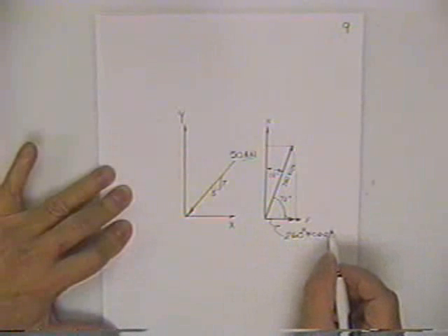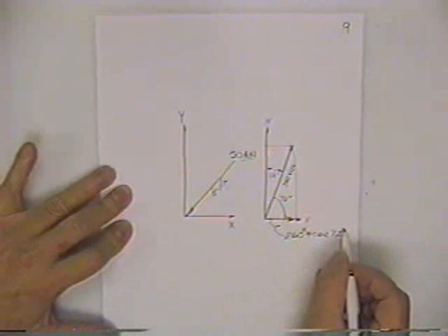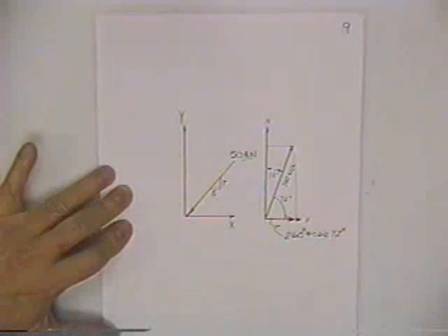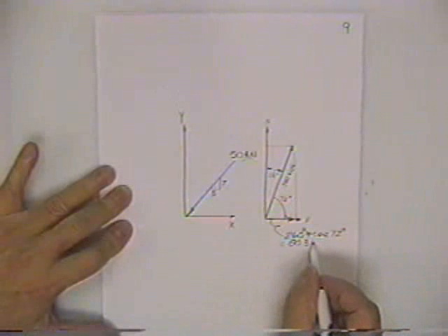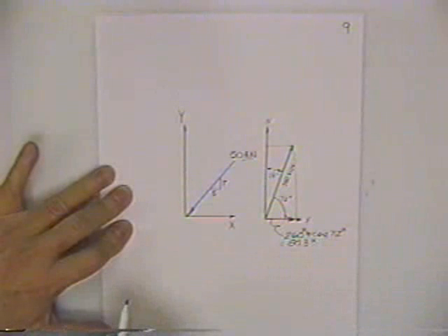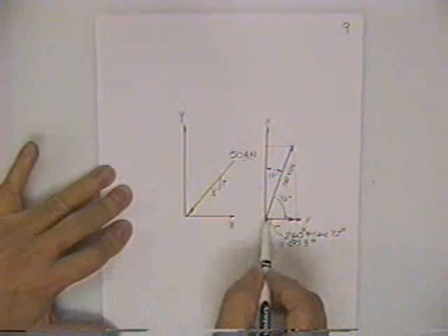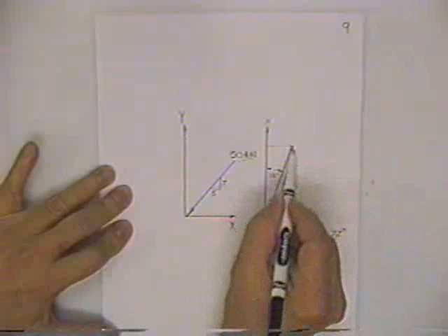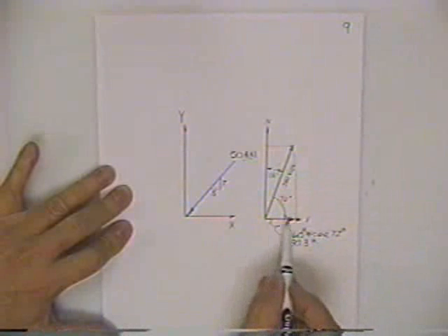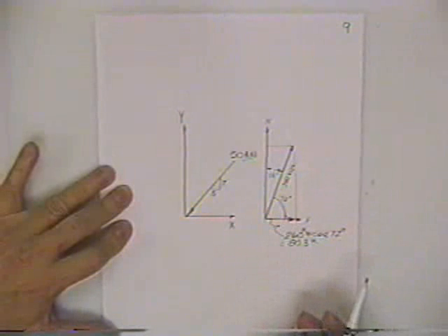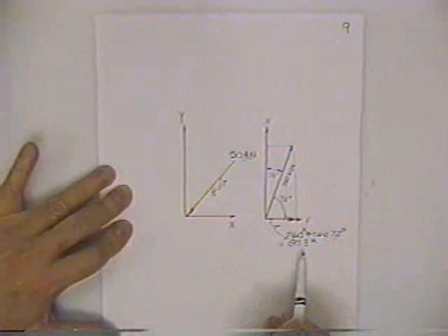Then 260 kips times the cosine of 72 degrees. I've got a friend of mine here with me running a calculator and the camera, so 80.3. Now you should be able to also tell if it is reasonably accurate, because if this thing is about 260 inches long, then I would say indeed this side of this triangle is about 80 inches long. So 260 kips, about 80 kips is probably correct.